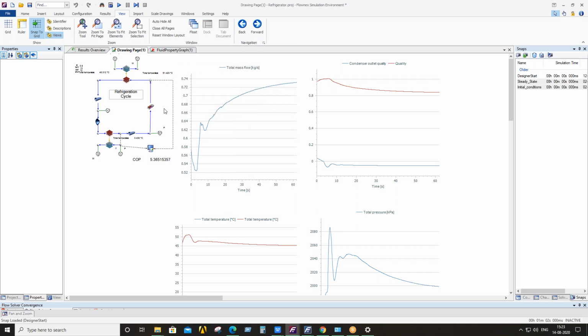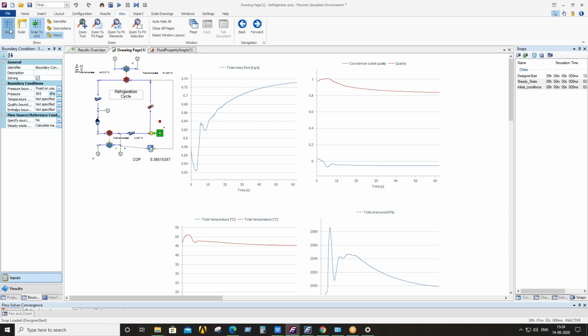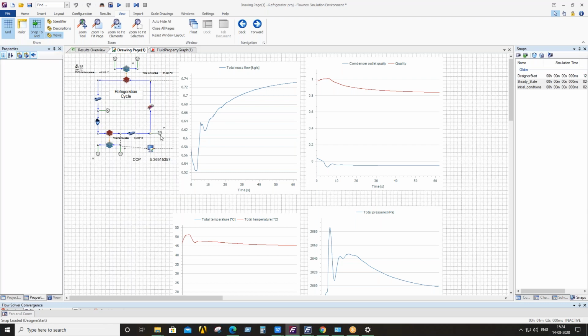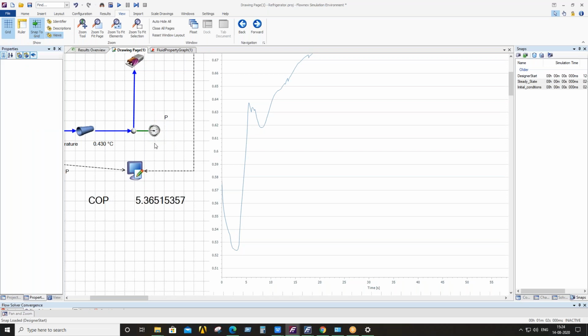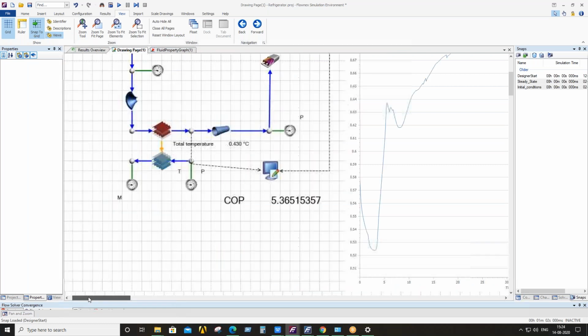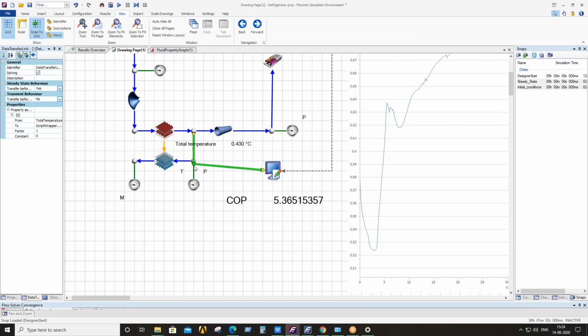Totally different, because in the reverse Brayton cycle, you use a turbine to expand the air. That is for the air refrigeration cycle. But when you go for a refrigerant, you have to use the vapor compression cycle. Yes, sir, I get it, my mistake. That is for the air refrigeration cycle, not the vapor compression cycle.